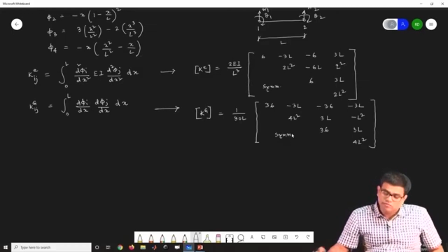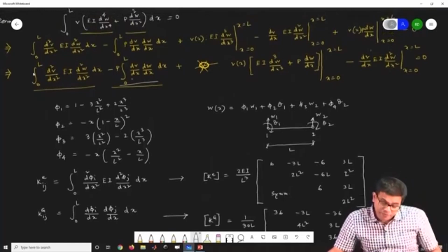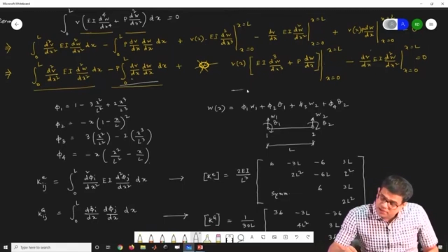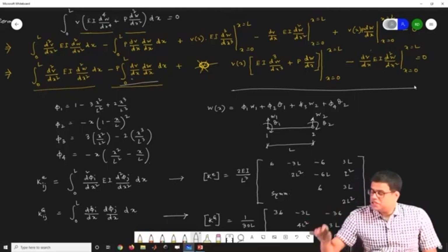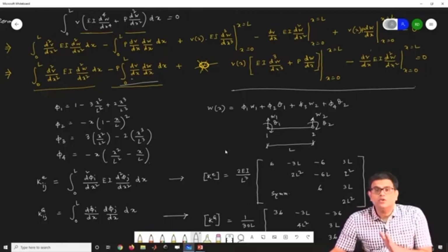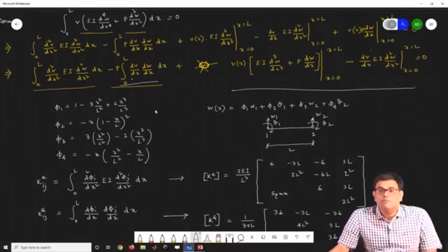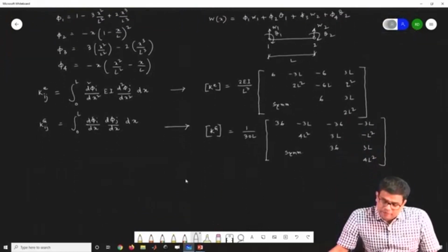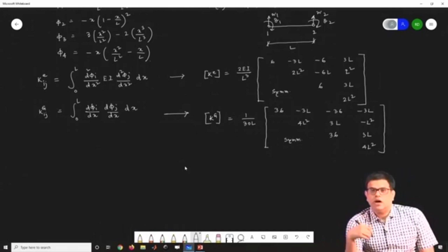Likewise, if I come back to this equation, this is my standard weak form. Now these terms are the boundary terms, so these terms will generate my boundary equations. That will go to the other side of the equation, and this term will give me the stiffness term, including the geometric stiffness. The other procedure is very simple. Again you will assemble it as per the finite element discretization.